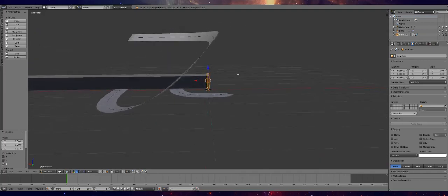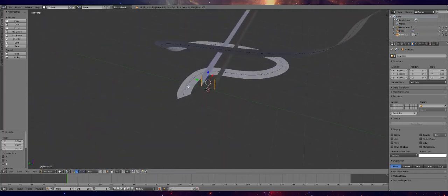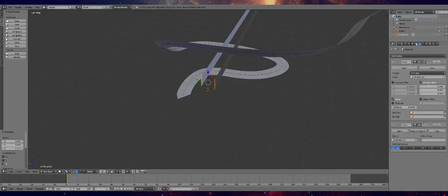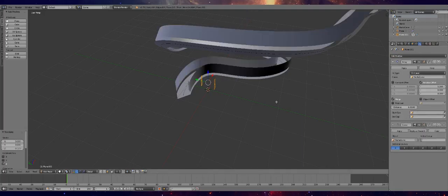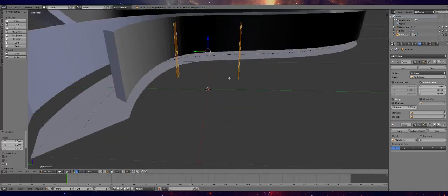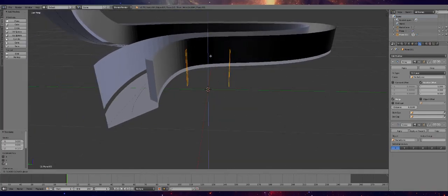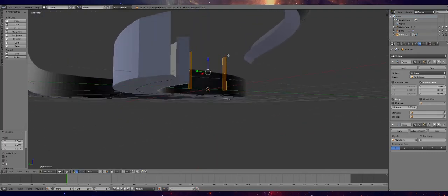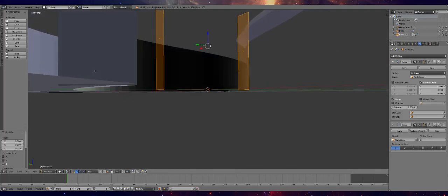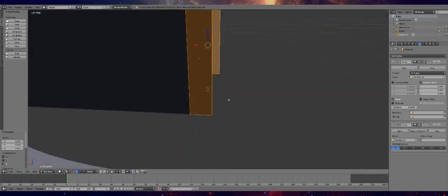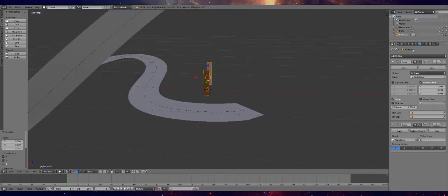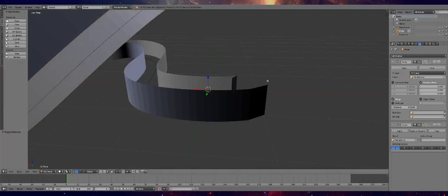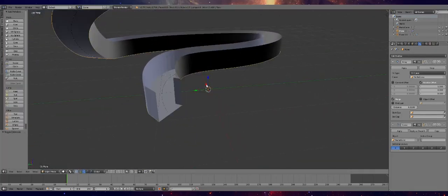Ideally, you will want to see stuff, right? So you can see that I don't see the curve here in this edit mode. But to do that, you have to go into the modifiers and click this little box with the points. That means it will preview the edit mode as you are editing it. So round about here is good enough. Actually, I went a little bit over, and this is not ideal. So let's do it like that. That's perfect. I'm gonna uncheck that because I really don't like editing my shapes with that modifier on. And I'm gonna uncheck it for both because hey, I don't like that.